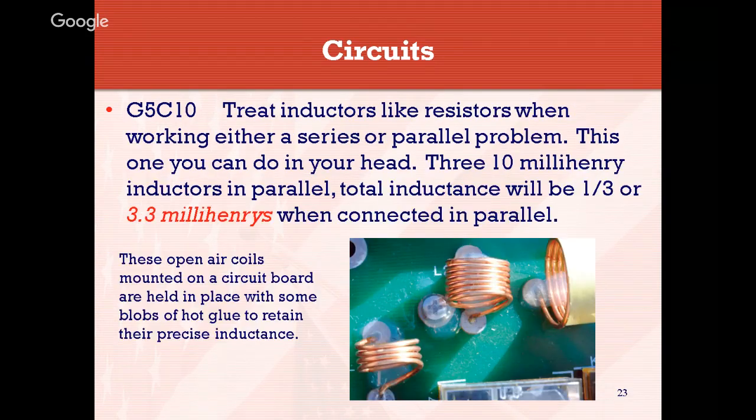One thing to do is to treat inductors like resistors, is what I was just saying, when working either a series or a parallel problem. So this one's pretty easy. You can do it in your head. You've got three 10 millihenry inductors in parallel. Think again, resistors in parallel. So the total inductance will be about a third of, and they're all the same value, around a third of what your total inductance is, 3.3 millihenries.